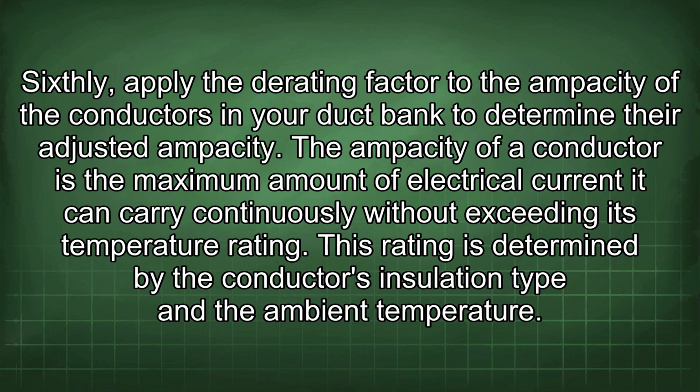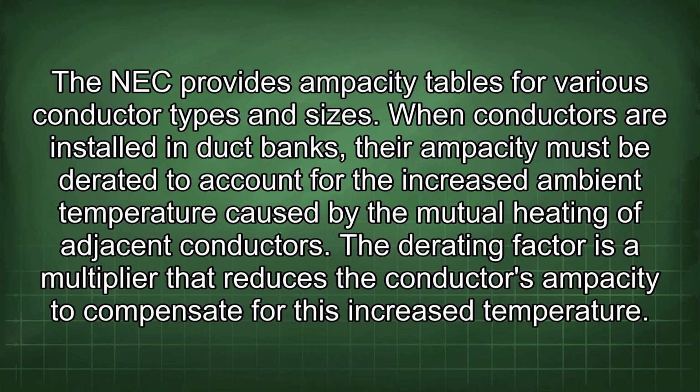The ampacity of a conductor is the maximum amount of electrical current it can carry continuously without exceeding its temperature rating. This rating is determined by the conductor's insulation type and the ambient temperature. The NEC provides ampacity tables for various conductor types and sizes. When conductors are installed in duct banks, their ampacity must be derated to account for the increased ambient temperature caused by the mutual heating of adjacent conductors.